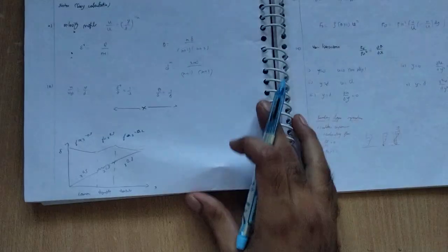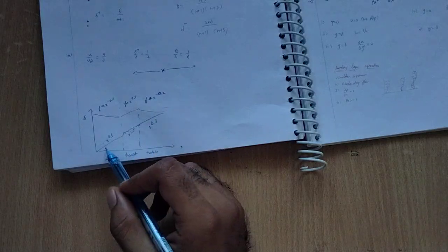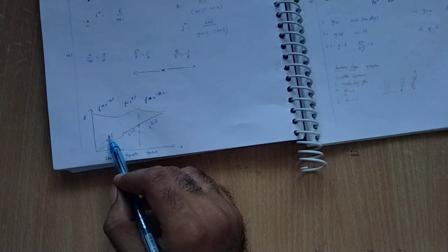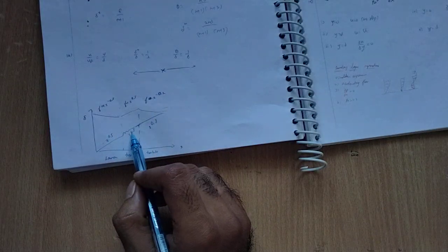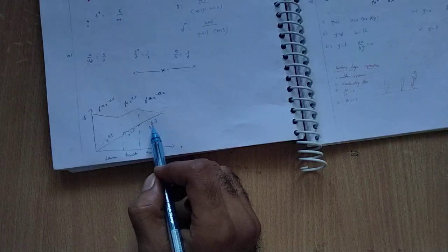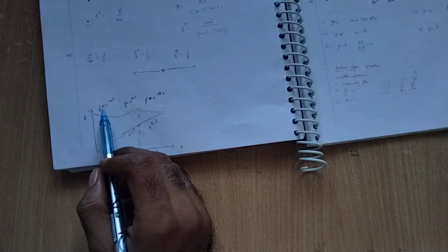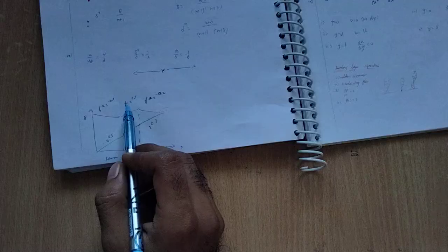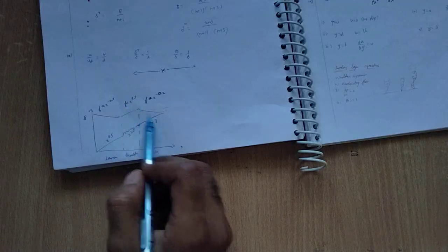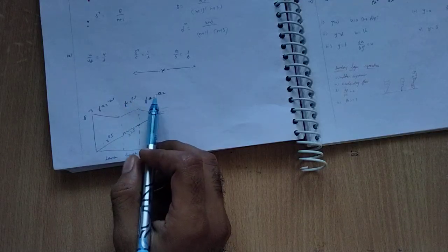Next is this, which is also a little bit important, so don't get confused. Here, for laminar flow the exponent of x is 0.5, for transition x is 1.5, and for turbulent x is 0.8. But for friction, you can see F is directly proportional to x power minus 0.5 for laminar, and this one will decrease, F directly proportional to x power minus 0.2.